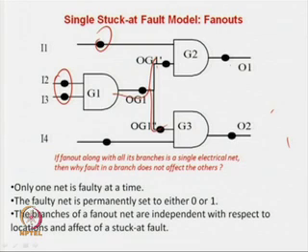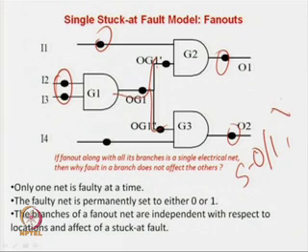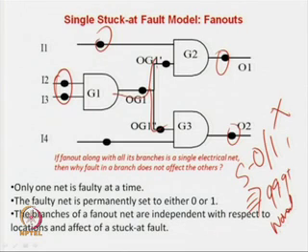Rather, we are trying to say that our circuit has no stuck at 0 and stuck at 1 faults. Then it implies there is a 99.9% plus chance that the circuit is normal. But we are not claiming the other way around, that if the circuit is normal then there is no stuck at fault. So what we are saying is that we verify that the circuit has no stuck at faults, then it is 99.9% likely that the circuit has normal behavior.